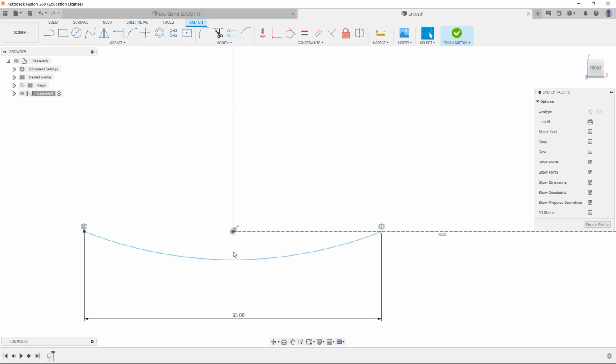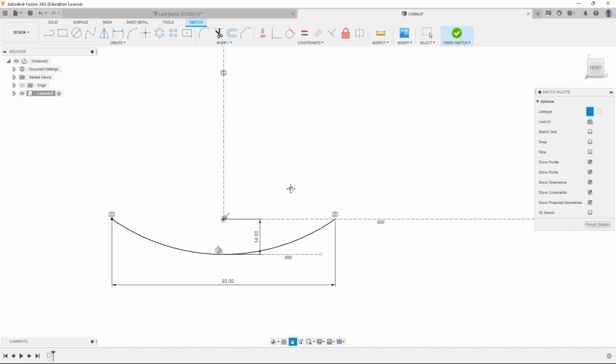And here, see clearly. Select construction line again. The toggle for it on keyboard is X. So press X on your keyboard and L for line. And here at the midpoint, draw a horizontal line. Okay. So we need this for dimensioning this distance. So D for dimension. Keep it 14 millimeters. That's it.